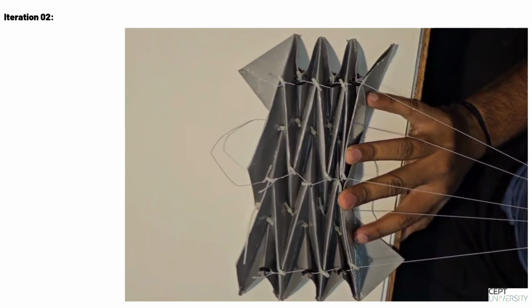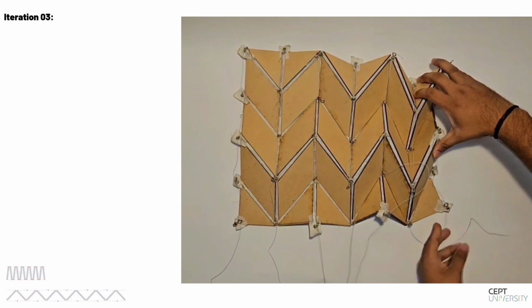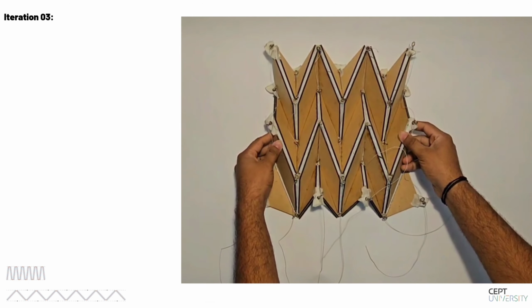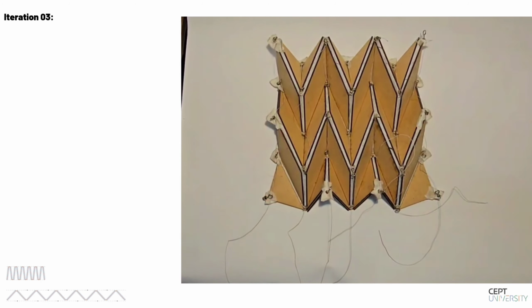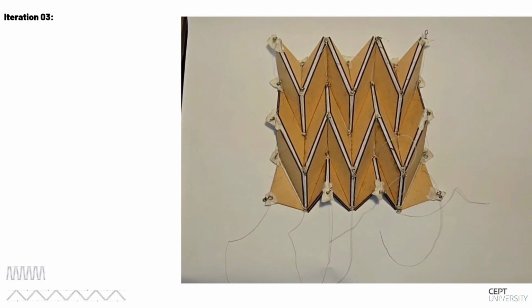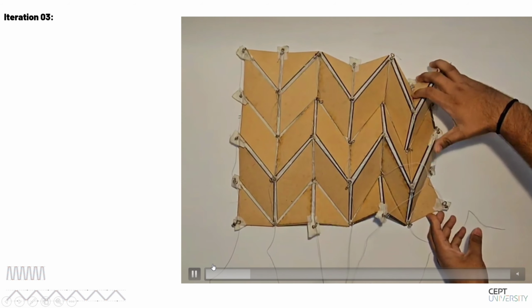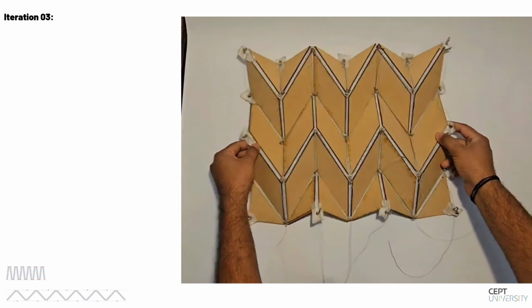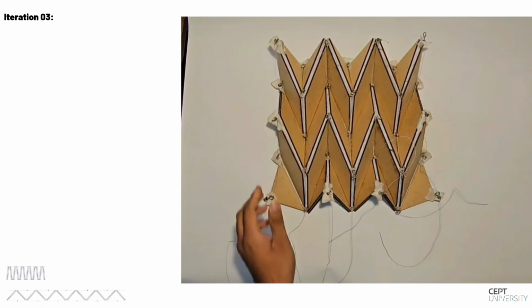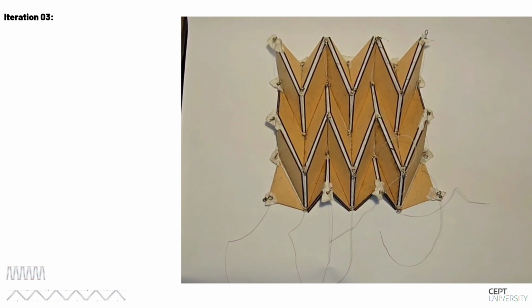To address the issue of individual control, I integrated fabric between rigid panels, forming a three-layer sandwich. The fabric acted as a flexible hinge, enabling all modules to fold or unfold collectively, creating a unified and responsive surface. Though the fabric system enabled unified internal folding, the absence of edge mechanisms hindered controlled deployment, making large-scale operation unreliable, inconsistent, and dependent on manual intervention.